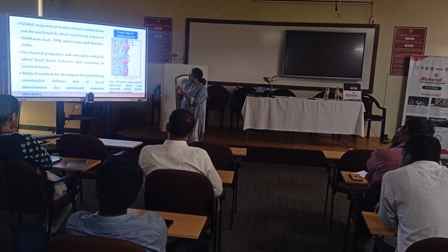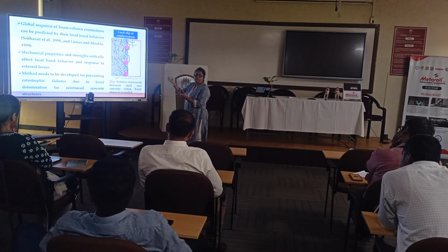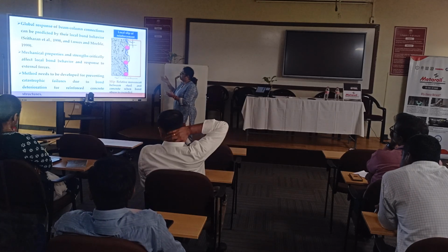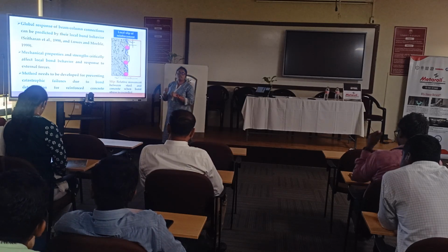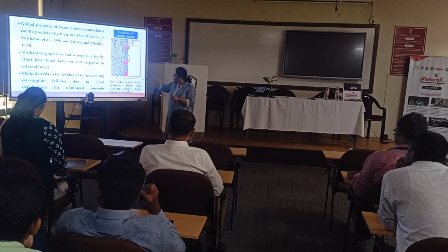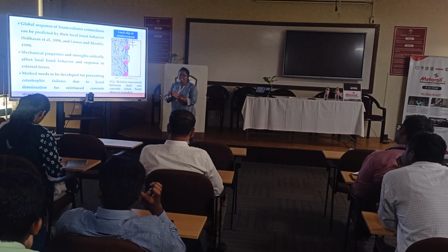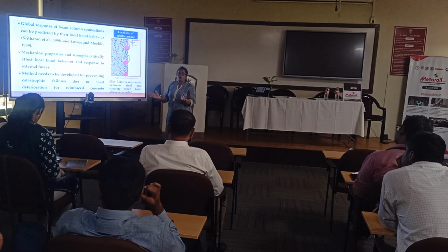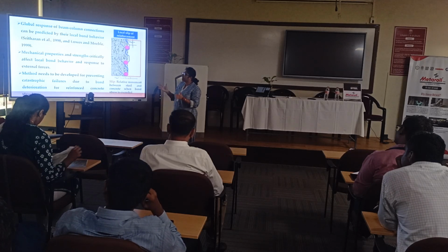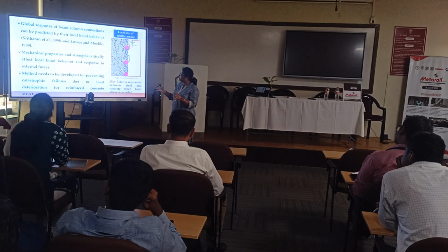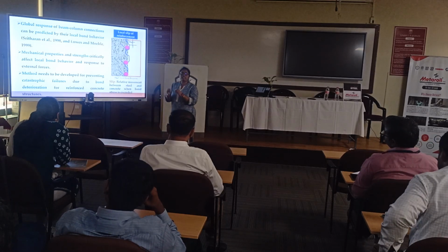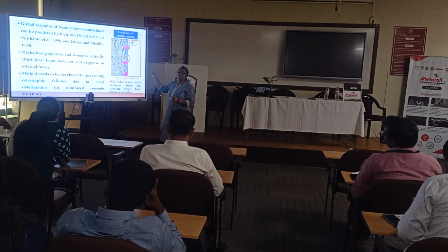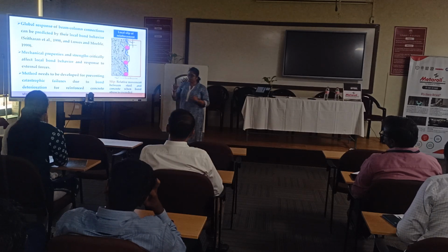Then, if the steel has a higher grade, like Fe 415 or Fe 500, with a larger diameter and higher strength, we try to crush first the concrete surrounding the steel, and then it propagates further radially. So it is called splitting, the split tensile failure, or splitting of the concrete. We see that once the concrete crushes, it radiates completely as a failure behavior.